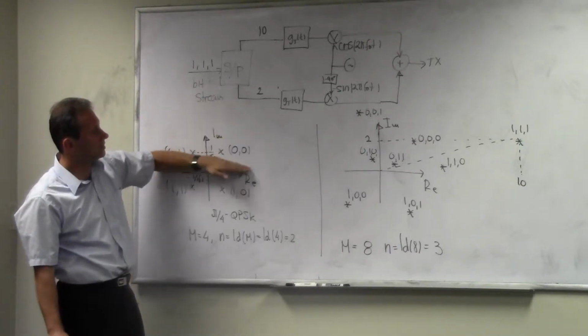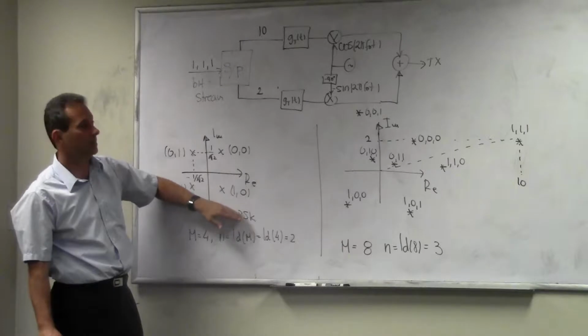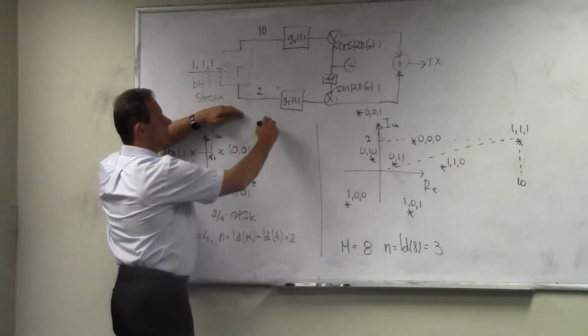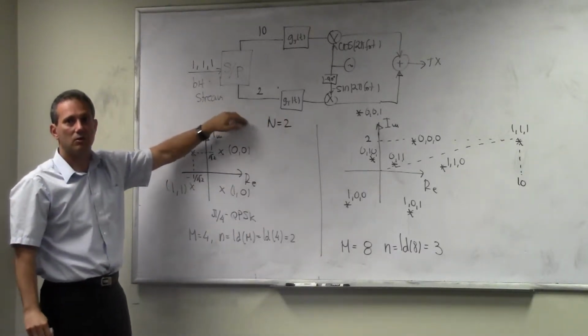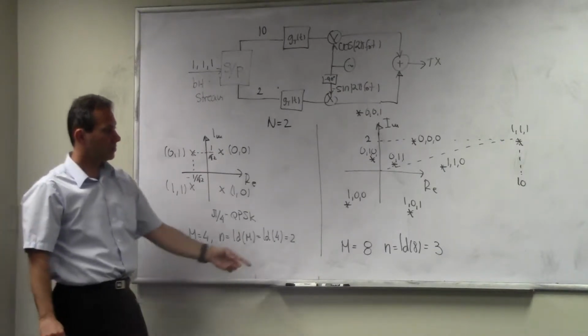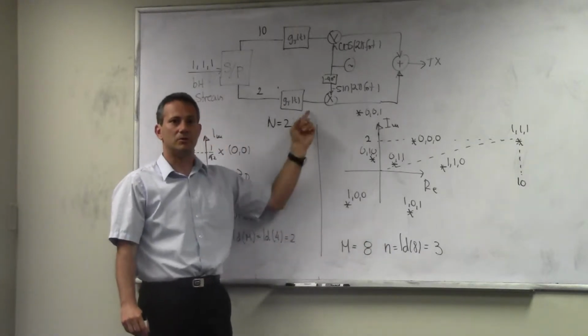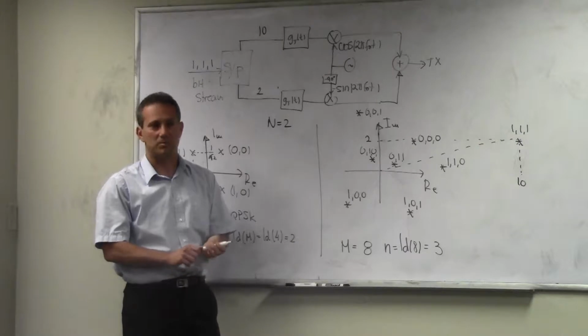The dimension here is added as you go to the higher dimensional signal. But as long as you stay with n equal 2, meaning that you have two vectors in your basis, you can devise schemes where you encode any number of bits per symbol. You just have to pick enough symbols in this constellation plane to accommodate a certain number of bits per symbol.